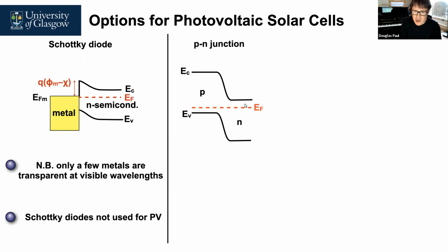What is done is that we put impurities that donate or capture electrons, creating holes in the valence band, and we put them beside materials where we put in impurities that basically donate electrons up to the conduction band. The first one's called p-type, the second one's called n-type, and due to equilibrium, again, you don't need to know so much about this for the course, we need to have the average energies in both the same, and that creates a difference so that we end up with this built-in electric field, what's known as a p-n junction.